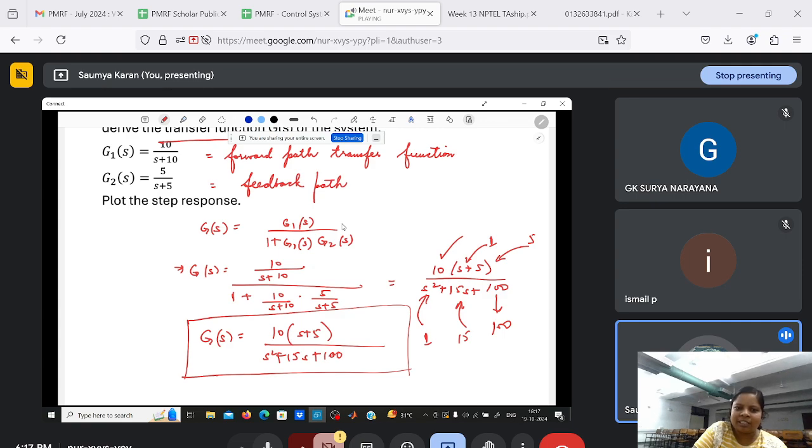Okay. So in the step response, yeah, this looks good. You can see that we have overshoot here. Then from here it goes down and it settles in this 2% or 5% band, whatever. MATLAB takes into account the 2% band. Okay. So this gives you the step response.